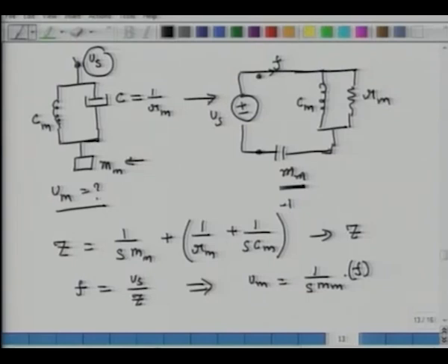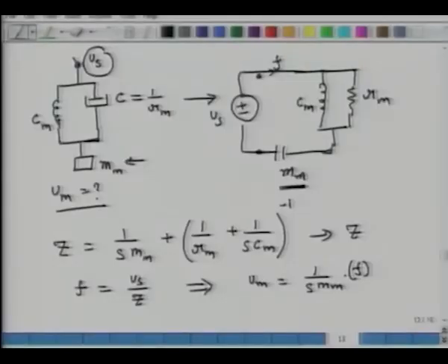So in this whole exercise, what we have done today is establish several equivalents between resistance and a dashpot, a spring and an inductor, and between mass and a capacitor. And then force translates to or becomes equivalent to current, and velocity transforms to voltage. This is one way of establishing the equivalences.